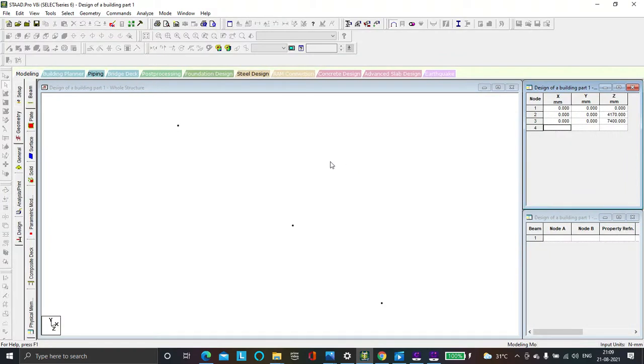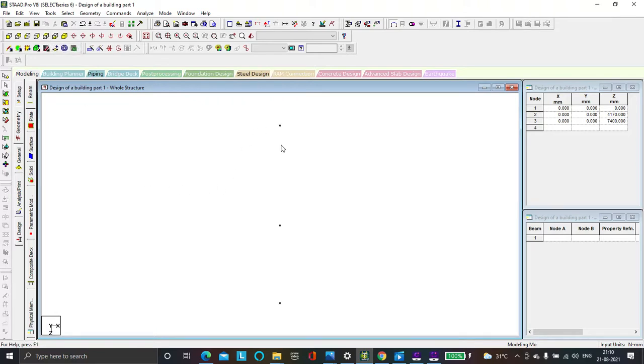When you come here, we see that it is best that we turn this view into a plan view. As I said earlier, these options represent from which angle or which side we view the project from. So we're going to view it from the positive y-axis. That's the plan view. I'm going to put it like this.